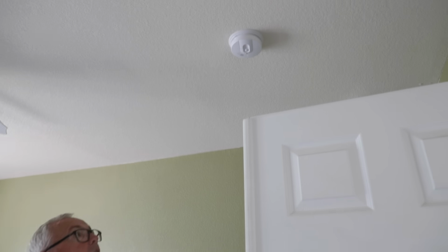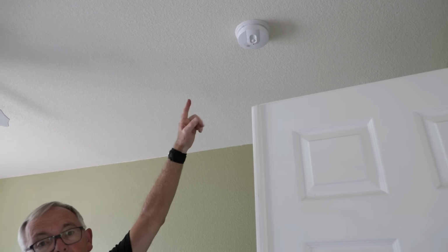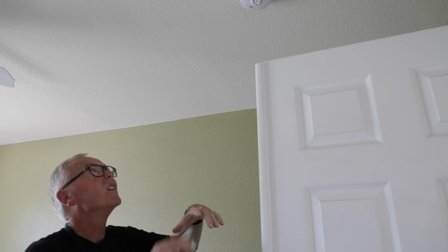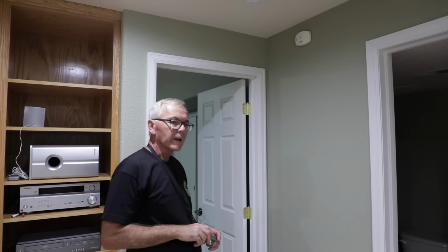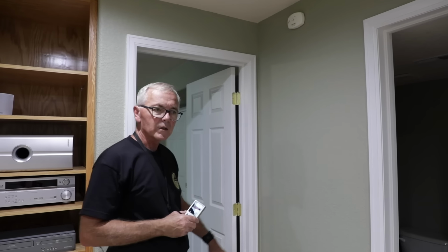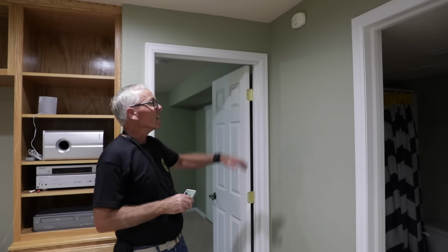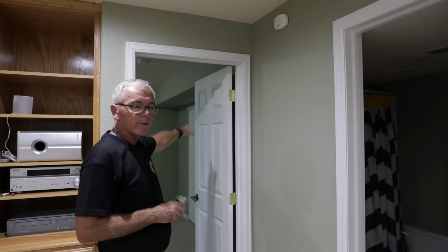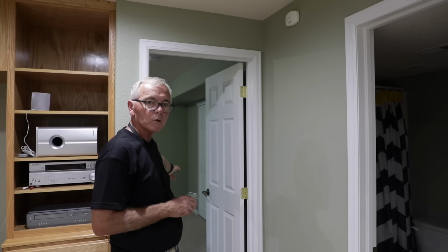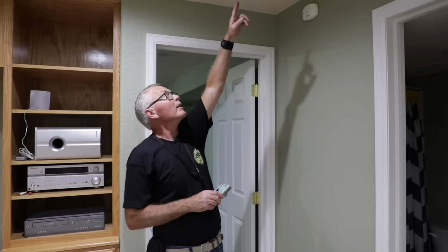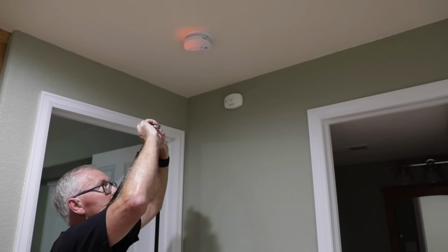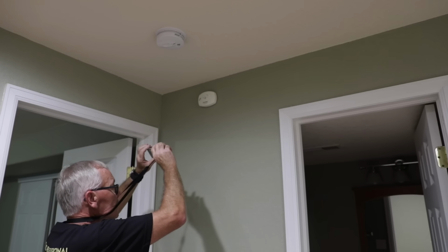So we also have to check for the presence of smoke detectors as well. I'm in the master bedroom here, and I can see right here on the ceiling that we have one. And I also noticed in the other bedrooms that there was also a smoke detector. So I am going to take a reference photo. The next location I'm looking for a CO detector is close to the bedroom that's in the basement. And I can see up here on the wall that I've got a battery operated carbon monoxide detector, and it's well within the 15 feet range that's required to be close to the bedroom. Also above here in the basement, we've also got smoke detectors. I'm going to take some reference photos, and I will document these in the report.